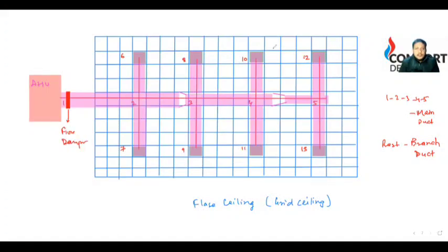And after that जो हम use करेंगे, it will be your VCD, that is your volume control damper. तो एक VCD यहाँ पे लगेगा, एक VCD यहाँ लगेगा, and उसी तरीके से एक VCD यहाँ पे लगेगा. So all these are your VCD, volume control damper, so that it can decide how much air. So the quantity of air will be decided by this VCD. So these all are VCDs. So I will write here this as VCD, that is your volume control damper.